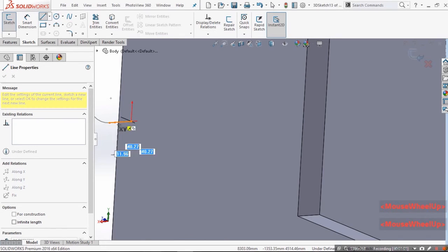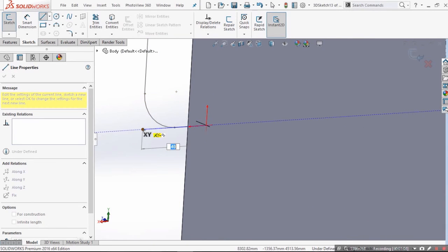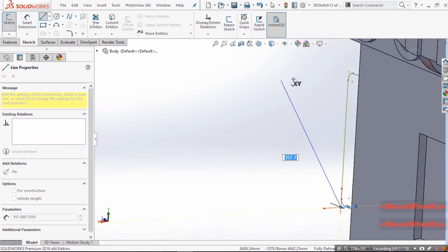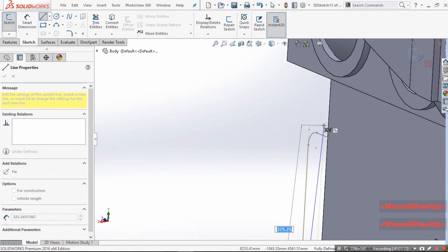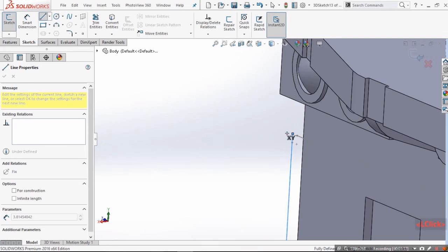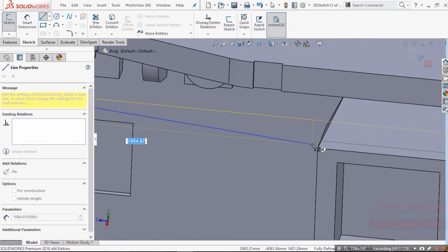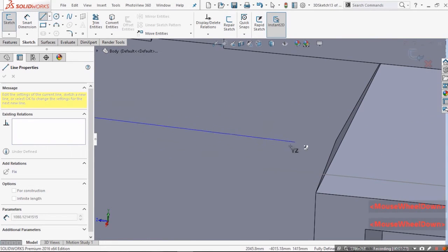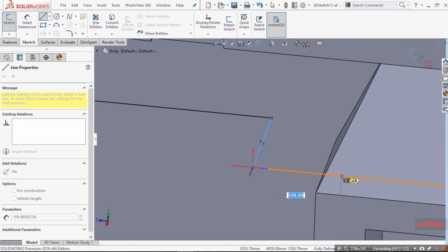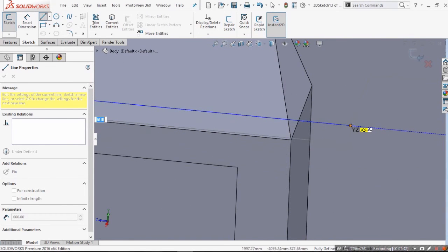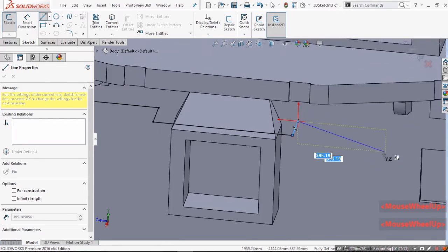Spot the center point of the 2D sketch circle and drag that line up to a certain distance. Now change the axis by pressing the tab key. So now you can extend a line in any plane you want. Sometimes changing the viewing angle can also change the axis, though it doesn't work all the time. To save time, I am using my old reference points to draw, but you will need to assume your own.